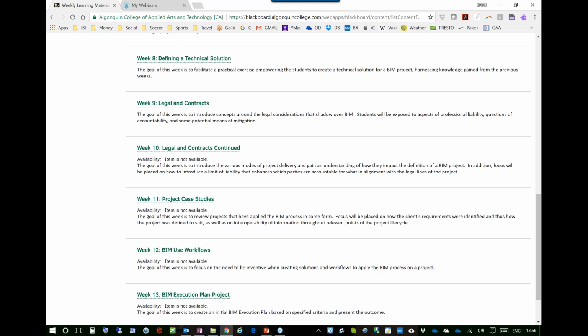So the contract, and using the architect's contract as an example, now has a clause, the most recent RAIC form, saying that if there is BIM applied on a project, use the BIM appendix. And there's now a BIM appendix that takes some base fundamentals that are expanded upon in an execution plan and puts them embedded into the contract. You will model, you will share the model, and you will use the model for these specific purposes. In the contract, understood, priced, and agreed upon. Therefore, anything in addition is in addition, anything not is in scope, and we all comply.